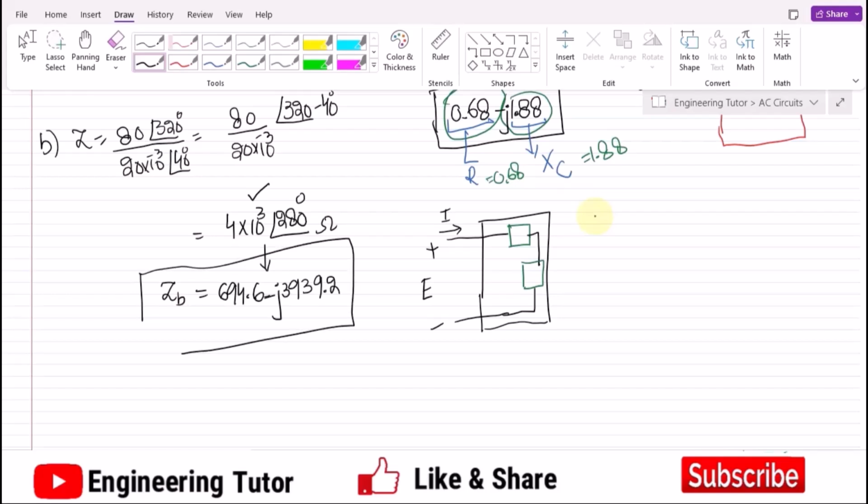So here the values, this one is the value for the resistance, while this one is for the reactance. And which type of reactance is this? This is the capacitive reactance because of the negative sign with it, so that is X of C. Okay, so now writing their values, I will get here this R, and here it will be jX of C with the negative.